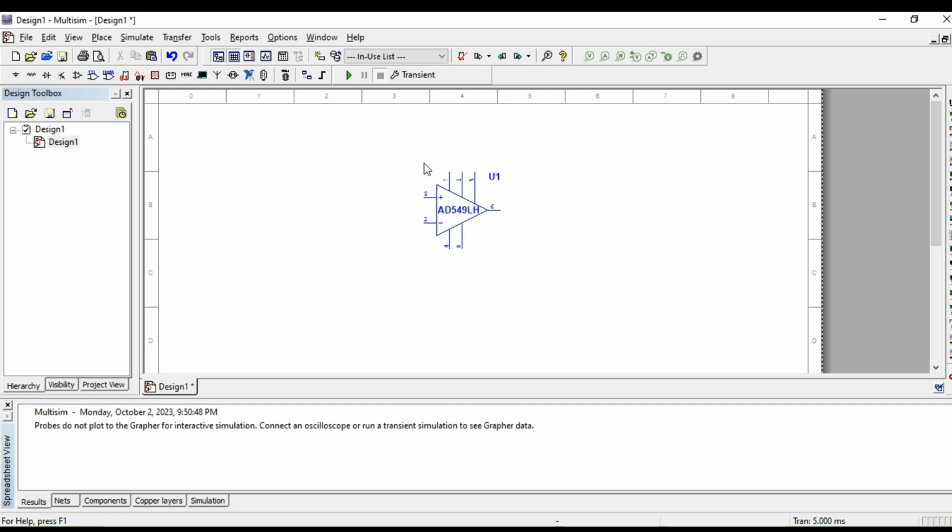I mean, the voltage peaks should not go beyond plus minus 10 volt. The reason is that if we touch the power supply voltages, the output voltage will be clipped and we will not know if we are having the right output voltage or not.